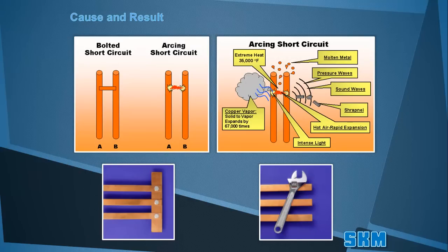Arc flash risk assessment estimates incident energy exposure from potential arc sources. To understand the purpose of an arc flash study, it is important to understand the difference between a traditional fault and an arcing fault. A bolted three-phase, phase-to-phase, or phase-to-ground fault creates high current that flows through the network and the current is contained within the network. Traditional fault studies are used to select equipment that can withstand and interrupt these short-circuit currents.